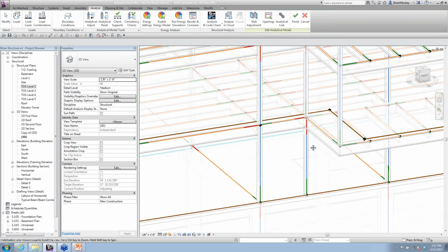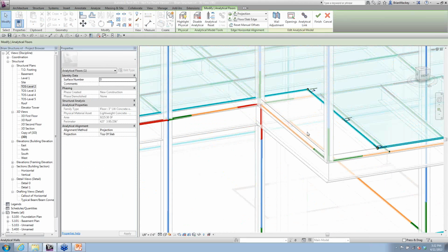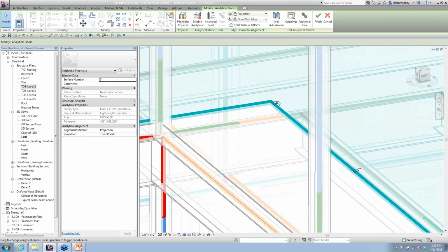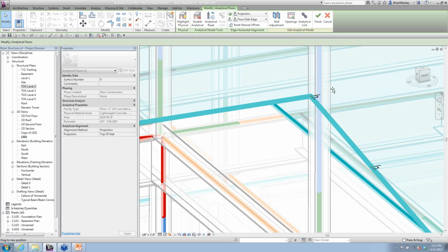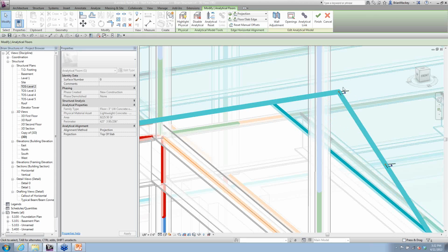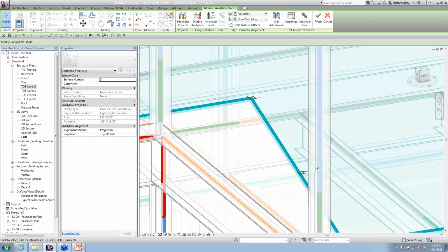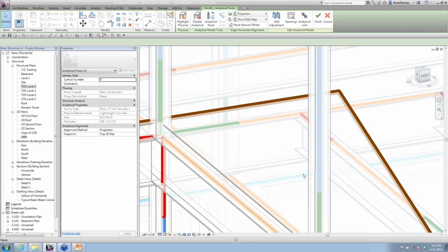And the one cool part about this is if I grab the slab, not everything else, you're going to see that, watch these little icons. When I adjust just this one node and I pull it out, notice how the nodes are like in the X, Y, Z axes, but the second I do, the nodes switch to be parallel. So now this is a perpendicular change, not a segmented change. And you're also noticing that now I can change the look of the analytical nodes. So I'm going to undo back to square.